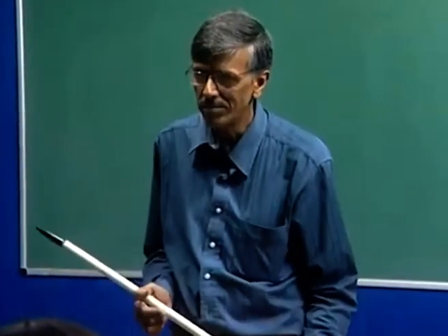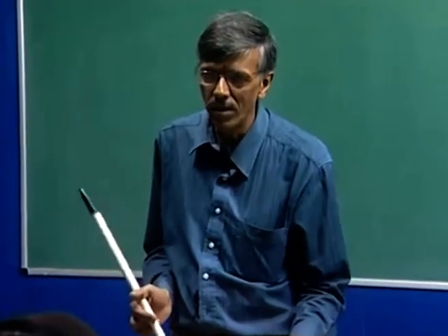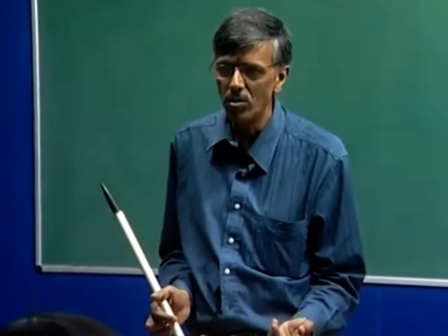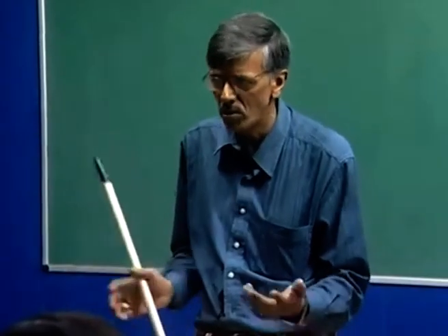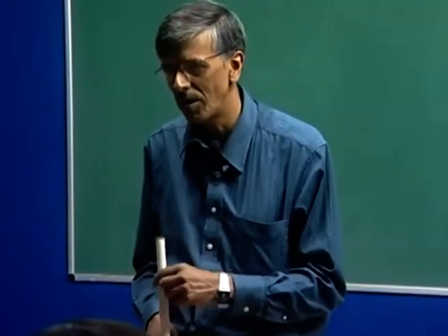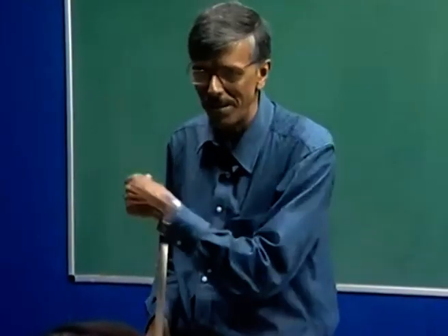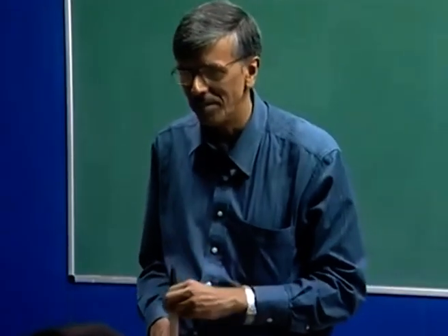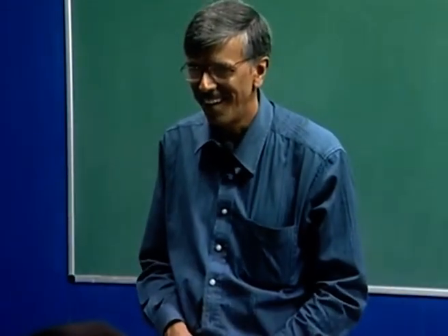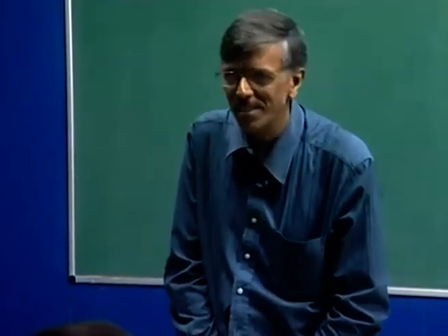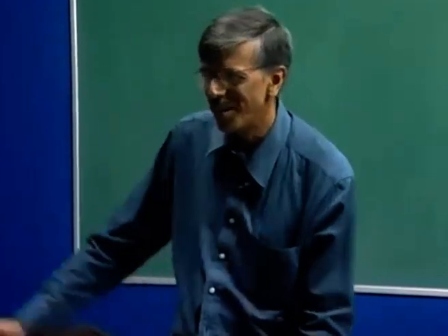What is the wavelength? What is our length scale here? Length scale is in terms of displacement thickness. So, if I have an alpha r, let us say 0.001, what is the corresponding wavelength? 2 pi by this. So, 2 pi by 2 pi into 10 to the power 3. So, how much is it? Some 6,000 delta star. How many tunnels in the world are made where your test section is 6,000 delta star?